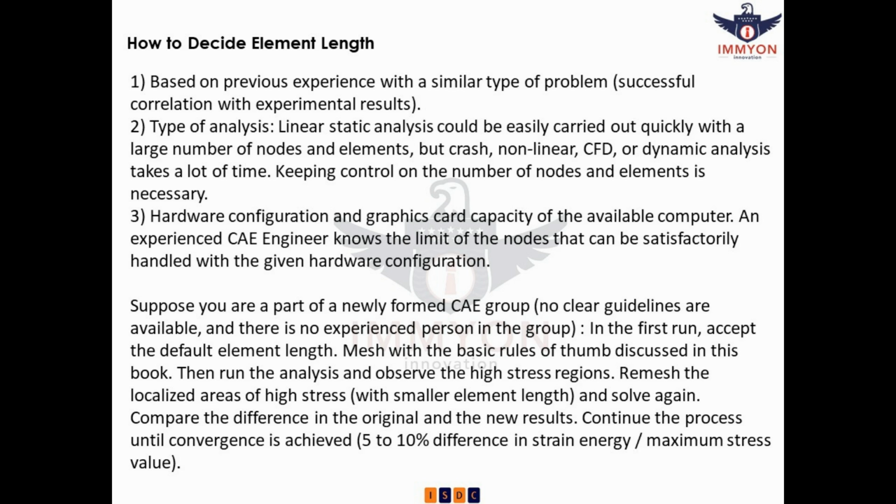Keeping control on the number of nodes and elements is necessary. 3. Hardware configuration, and graphics card capacity of the available computer. An experienced CAE engineer knows the limit of the nodes that can be satisfactorily handled with the given hardware configuration.